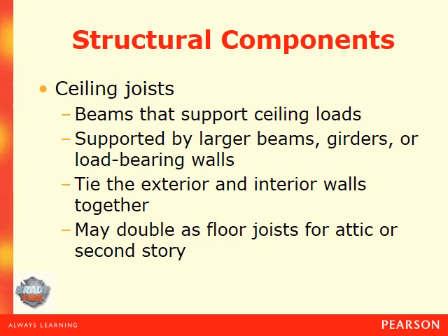Ceiling joists are beams that support the ceiling loads, and they are supported by large beams, girders, or load-bearing walls. They tie the exterior and the interior walls together, and they may double as a floor joist for attics or a second story.